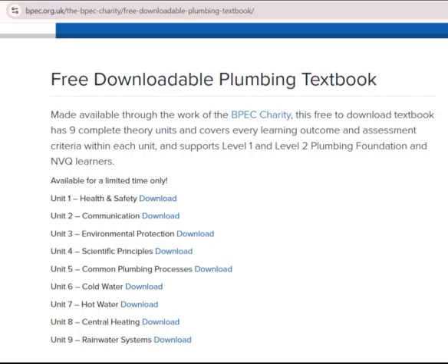Polypropylene: push-fit waste and overflow pipe, cold water storage cisterns. Polybutylene: push-fit hot and cold water installations, central heating installations. ABS, acrylonitrile butadiene styrene: water supply, potable water for apartments, offices, commercial installations, solvent welded waste and overflow pipes. Fiberglass: baths and shower trays.